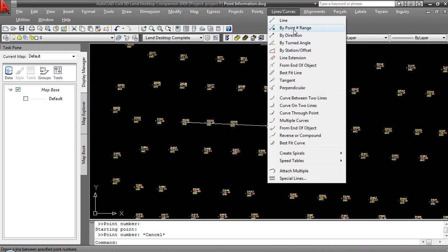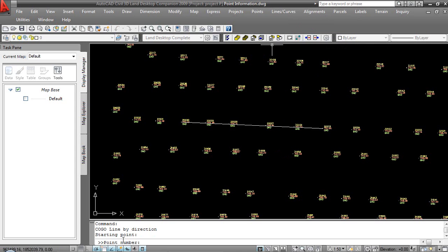All right, so even though I'm familiar with it, I still messed it up because it requires multiple commands for me to be able to do this effectively. At the same time, I'm limited by lines. If I wanted to create polylines, or what if I wanted to use this for inserting blocks, or worst case scenario, if you've ever turned on the .p or the .n or the .g operation, that's remembered forever. So if we start executing other commands like bringing in symbology, it's going to keep remembering those point numbers. So if we come into line by direction, now it's going to start asking for point numbers, and that's not going to go away until we hit .p to turn it back off,